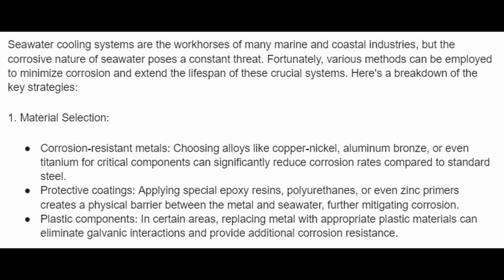1. Material selection. Corrosion-resistant metals: choosing alloys like copper-nickel, aluminium-bronze, or even titanium for critical components can significantly reduce corrosion rates compared to standard steel.